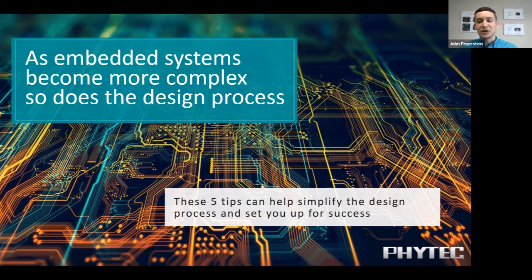By using a PHYTEC SOM, you can eliminate that additional overhead of reading through the documentation, doing the designing, the manufacturing, the testing, and successfully integrating a CPU, DDR memory, flash memory, power management, and so on into your embedded system. Our off-the-shelf solutions have already gone through those development and verification processes, and they're ready to plug into your application. For an example, I have a SOM here to show you that's based on the NXP IMX8M Mini. This is a BGA low-profile SOM that can solder down to a carrier board, incorporates the silicon from NXP, power management, flash memory, DDR, and all those things that I just touched on a moment ago.